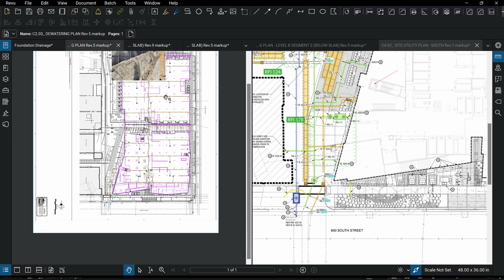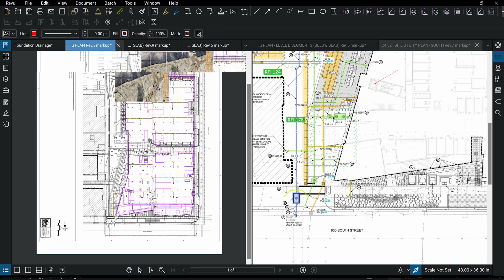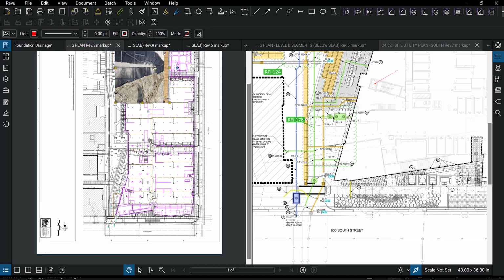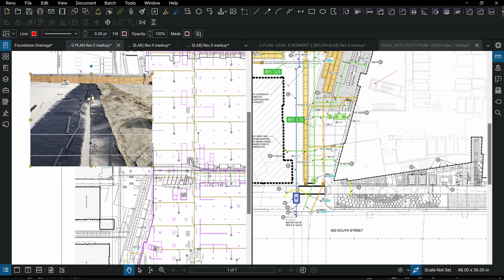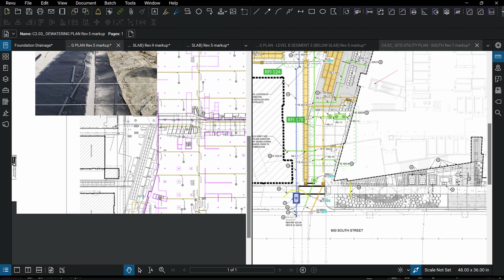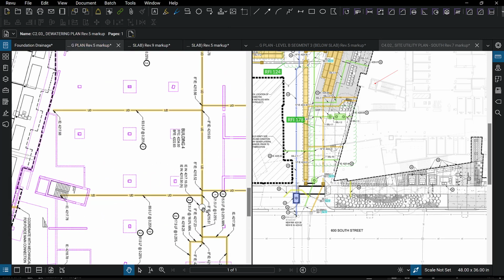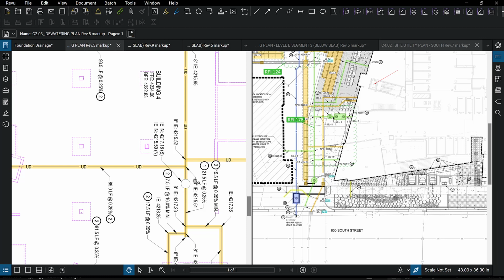So thinking through this a little bit, they're digging out underneath the footing foundation. They're digging trenches, putting the Mirafi fabric in, putting the pipe in. The gravel slopes, so the pipe's going to follow that slope when they put it together. They're going to bury it and put more gravel over. That is these pipes right here that they're putting in. The pipe is going all the way down to this sump pit. The sump pit's somewhere over here in the basement.